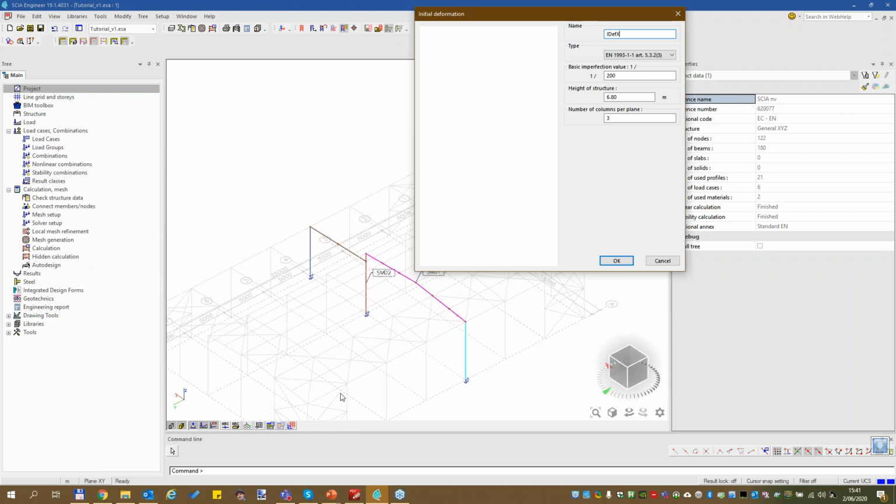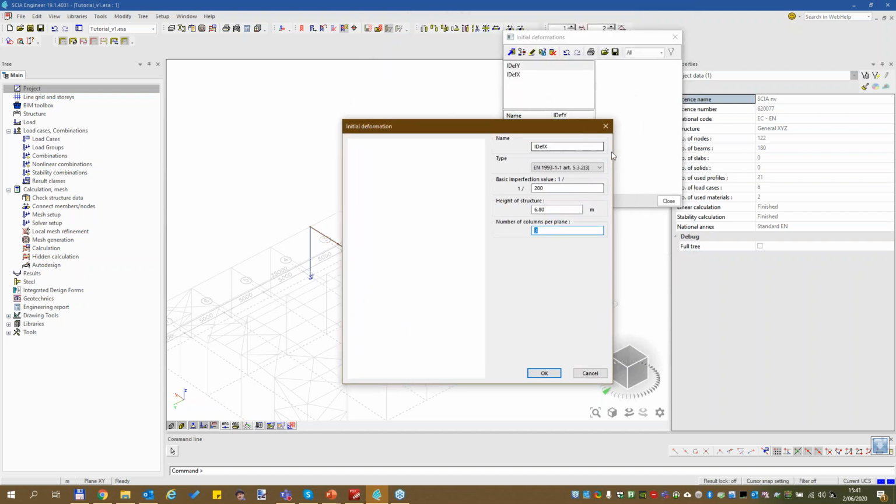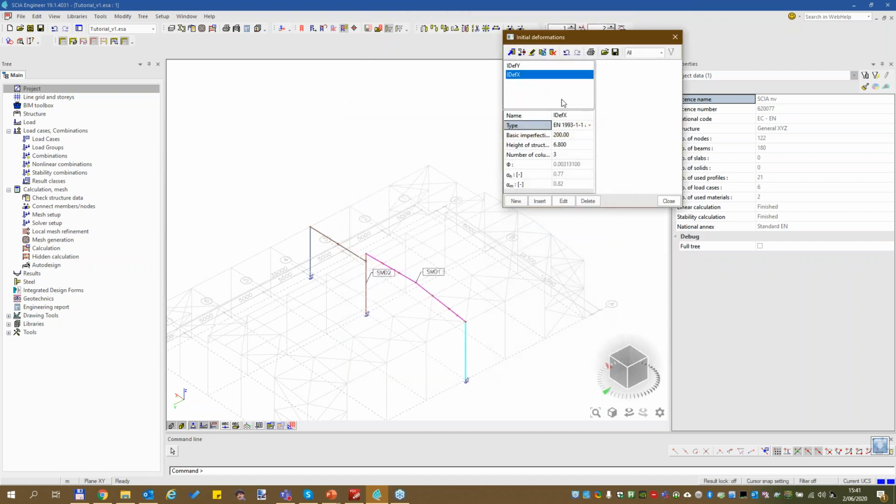It's just using common sense. You can see that the majority in the y direction have 3 columns. So that's why I'm using 3 for idefx. That's what you see right here. And for idefy, I'm using 8. So these 8, which you see right here, which is also here, and which is also here. The only ones that have 2 in the y direction are this one, column 1, column 2, and the same for this one and here. But the majority have 8.